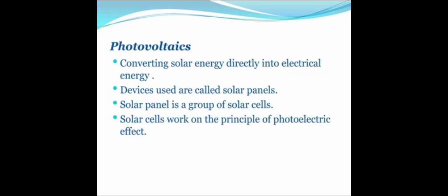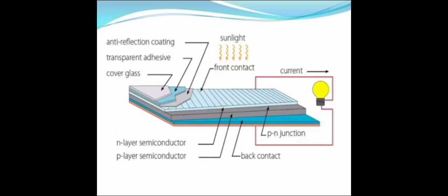Solar photovoltaic is a technology that converts sunlight into direct current electricity by using semiconductors. When the sun hits the semiconductor within the PV cell, which means photovoltaic cell, electrons are freed and form an electric current. Solar photovoltaic technology is generally employed on panels. Photovoltaic cells are typically connected to each other and mounted on a frame called a module. Multiple modules can be wired together to form an array, which can be scaled up or down to produce the amount of power needed.